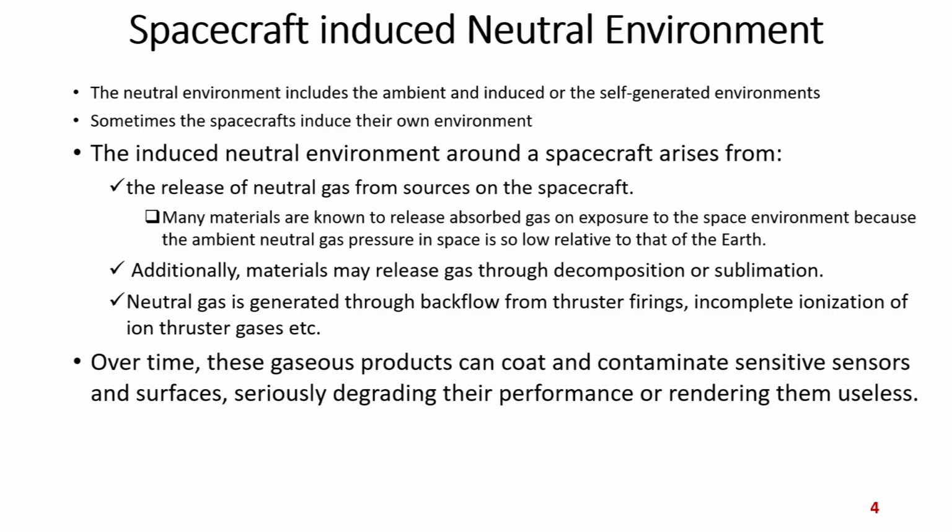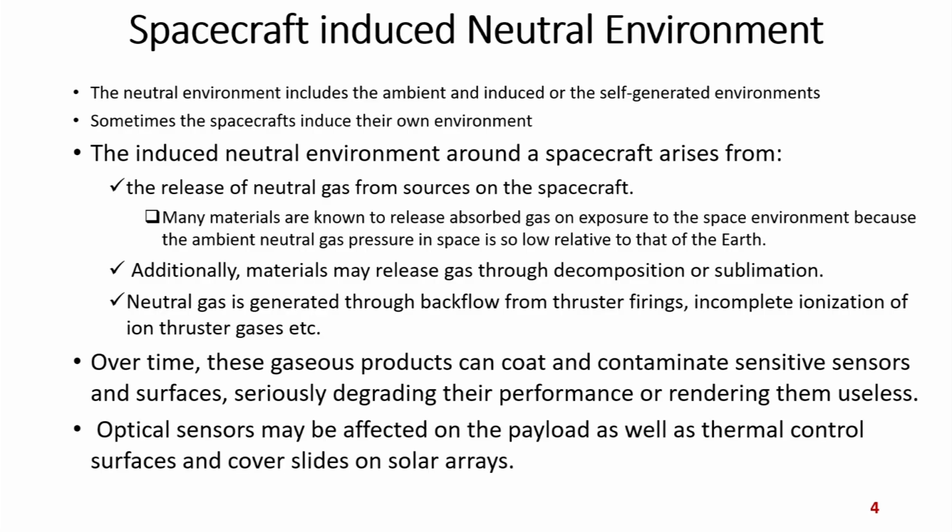Now, over time these gaseous products can coat and contaminate sensitive sensors and surfaces, seriously degrading their performance or rendering them useless. We will see, but I am just stating here that optical sensors on the payload may be affected, as well as the thermal control surfaces and whatever cover slides are used in the solar arrays.